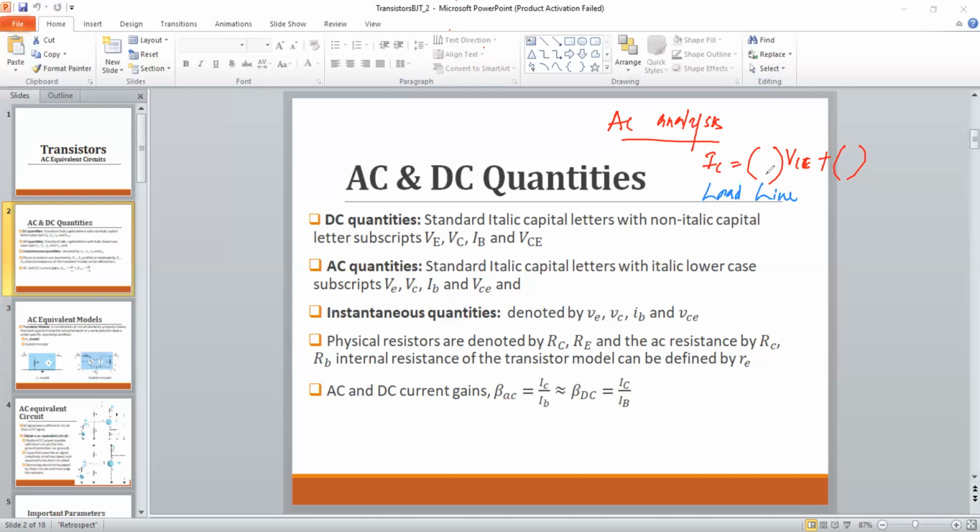Once you set the operating point of the transistor, we can identify the Q point values, base current and collector emitter voltage. Based on those values, we can easily calculate the required resistors we need to place in either the base terminal or collector emitter terminal. We discussed how we can select these different resistors in different arms according to the given current and voltage requirements of the Q point. It's just Kirchhoff voltage and current law, so you can apply KCL and KVL to this transistor circuit.